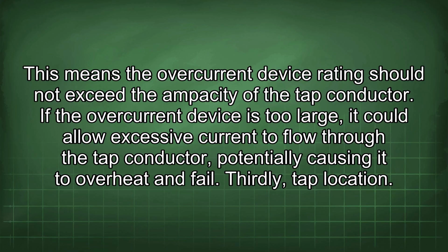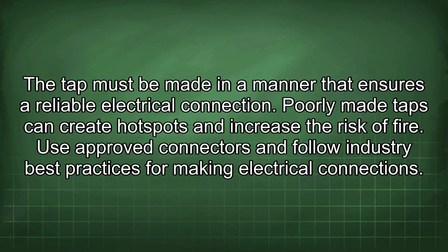Thirdly, tap location. The tap must be made in a manner that ensures a reliable electrical connection. Poorly made taps can create hotspots and increase the risk of fire. Use approved connectors and follow industry best practices for making electrical connections.